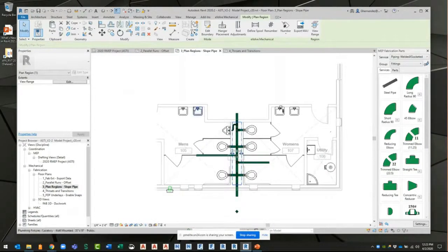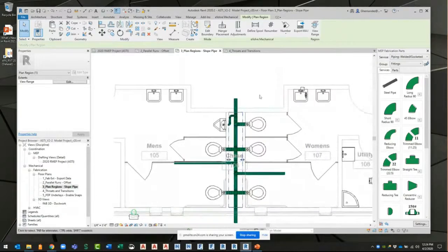It's for controlling a portion of the model so that you can set the view range a little bit different, so mezzanines and other things like that, but it's specifically for plumbing. This is going to be one of my big plumbing tips for my plumbing users, is they can use these here to keep the rest of the model displaying the way it's supposed to, okay?